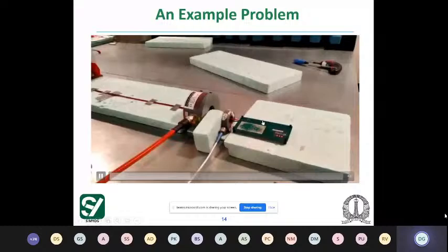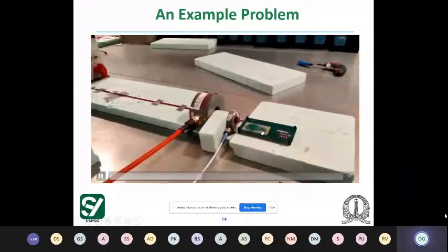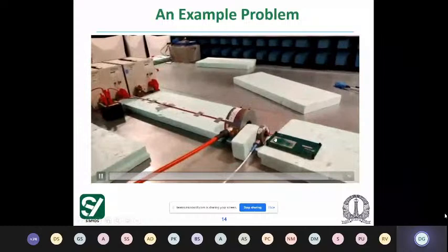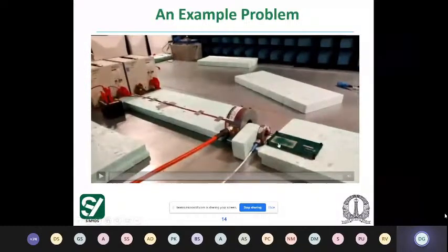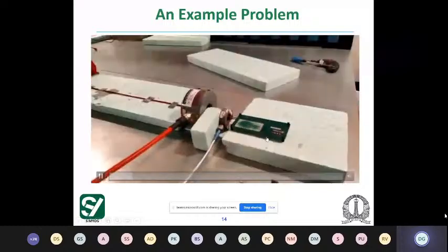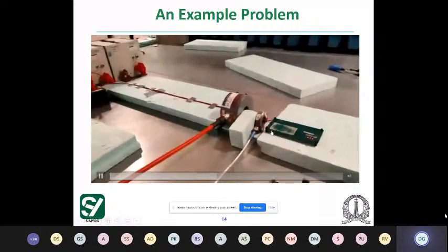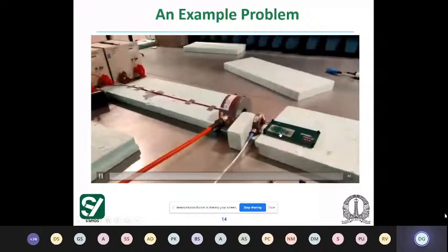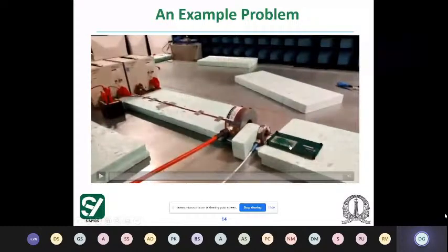This is a touch screen controller from Cypress, and you see that a lot in automotive infotainment systems today. The functionality of this test board is that if you press a button here, this LED is supposed to glow. It's a capacitive touch. When you press the button, the IC is sensing the change in capacitance and therefore triggering an LED. It could be triggering something else in the infotainment center and so on.